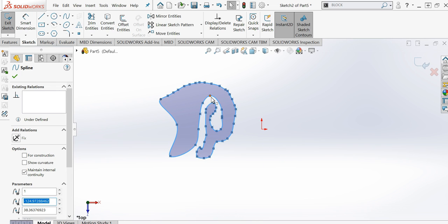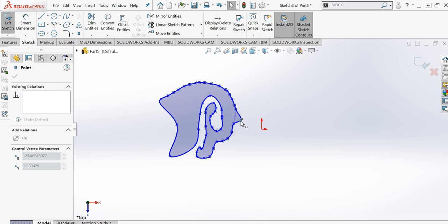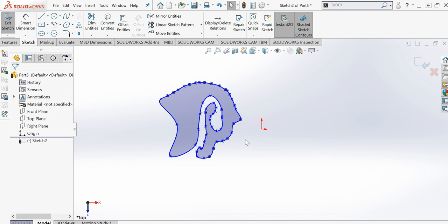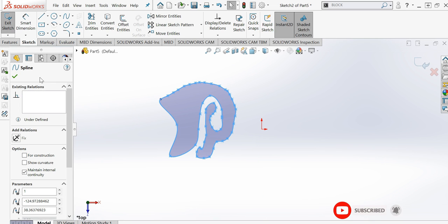Also, sometimes the dimensions are so critical, and if the sketch distorts when you are moving some points away from the required profile, then it will be difficult. So the block is just locking that. Just select this and choose Make Block.